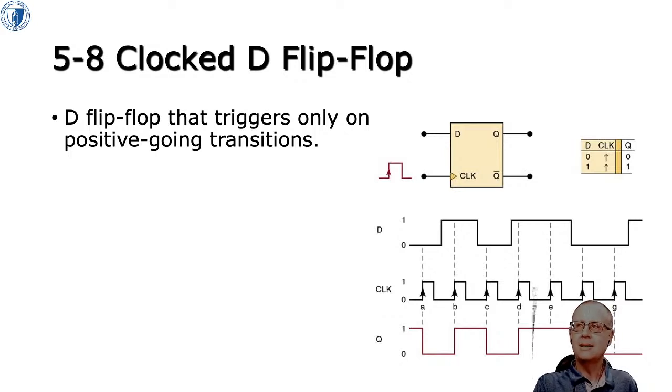Okay, here's a D flip-flop, and one way to think about the D flip-flop is that it's a delay, right? So the input on D gets transferred to the output on Q on the clock transition. Again, both D and the clock input are non-inverting, there's no bubbles on them. So when the clock transitions, whatever was on the input at D gets transferred to the output at Q.